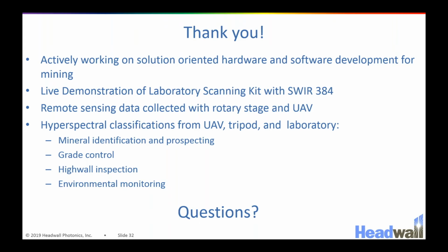We have found that our radiometric calibration is very stable and holds for a very long time. Basically, I would say you need to re-radiometrically calibrate if your lens gets really dirty. What I was doing when I was measuring that white spectralon tile was getting a full frame white reference and skipping the radiometric calibration part.